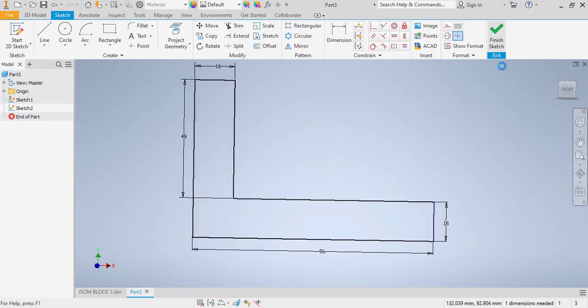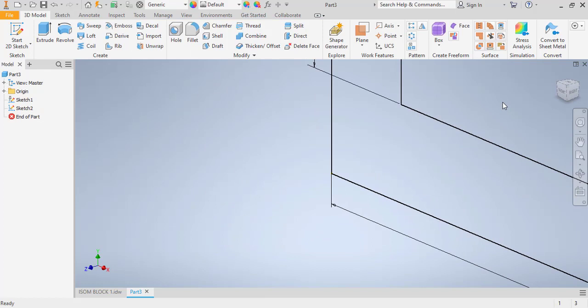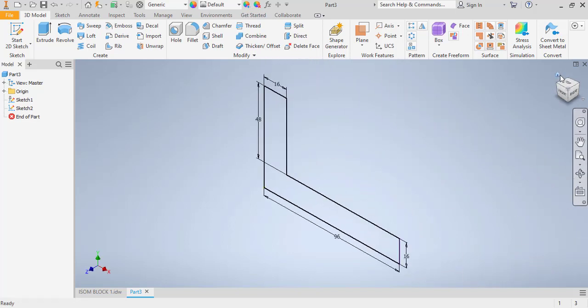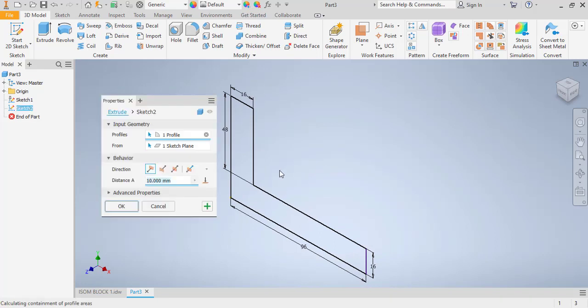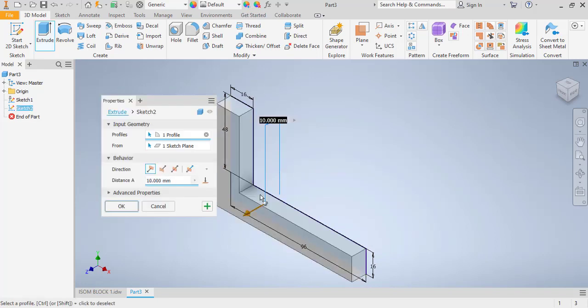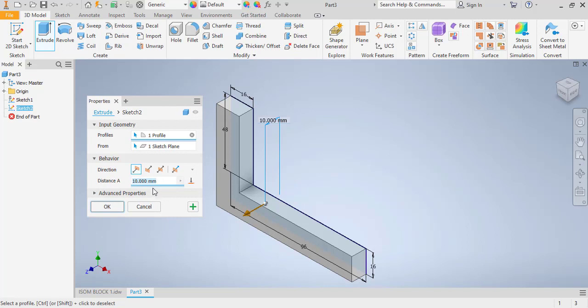So you click finish sketch, and you can also use toggle in between F5 and 6 to bring your drawing back to the previous position it was. But I can click also, you can use the view cube to position your drawing very well. Here we go. I will now go to the next level by extruding it by pressing the letter E on the keyboard, or you can click on the extrusion command here and you invoke this window, which you can dialog with it to get your end result.